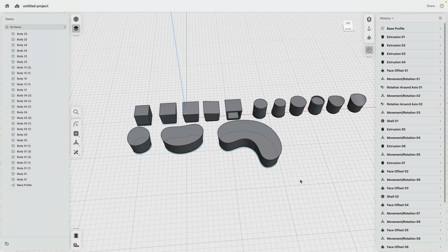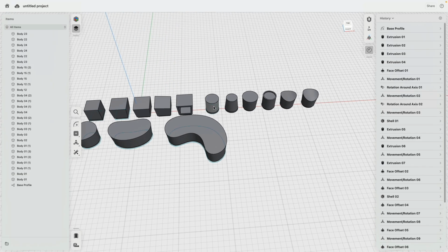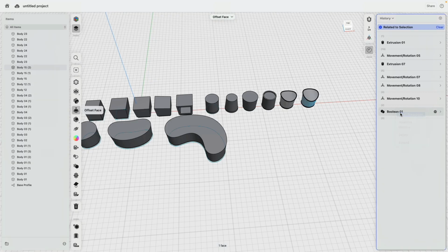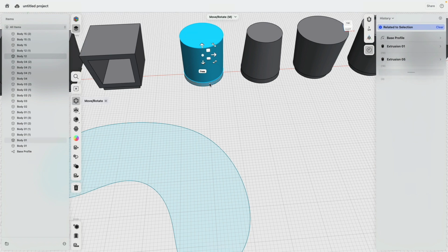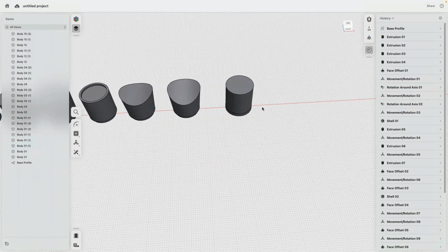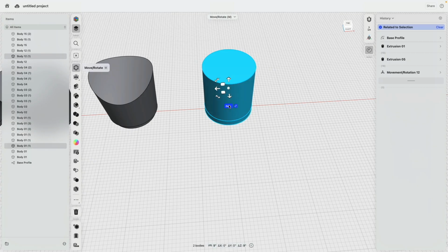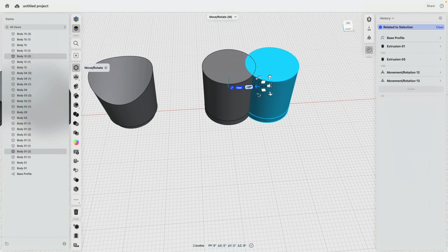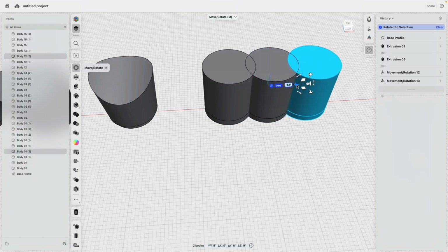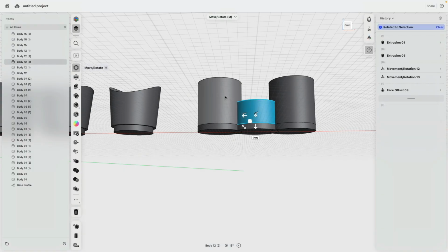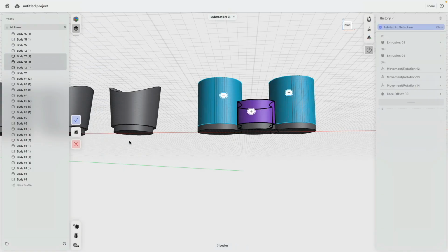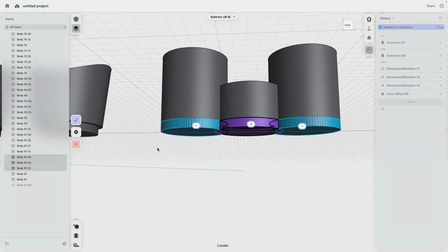I talked about when you model, ideas happen and generate. What happens if I have this as a stool and I would like to have a side table that is actually at a lower base? So when is this one made? Boolean, right click, insert breakpoint. You noticed that now this stuff is hidden. Here's a marker, and I know I could go ahead and select all this, make a copy, bring one copy over. There we are. Select this, make a copy, bring this over to intersect. So 13 and another 13. Thank you. And this one I bring down. There we are. Cool. So from this one, I want this and this to be removed, but keep the removed body. From this one, I want this and this to be removed.